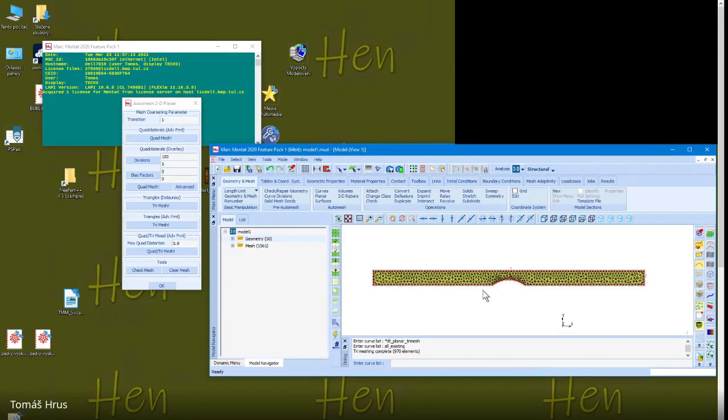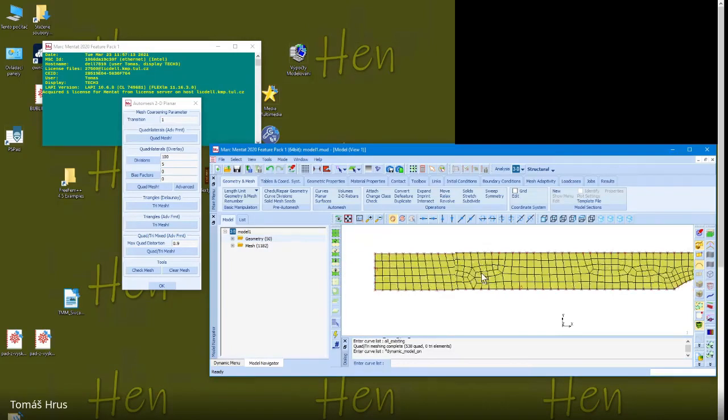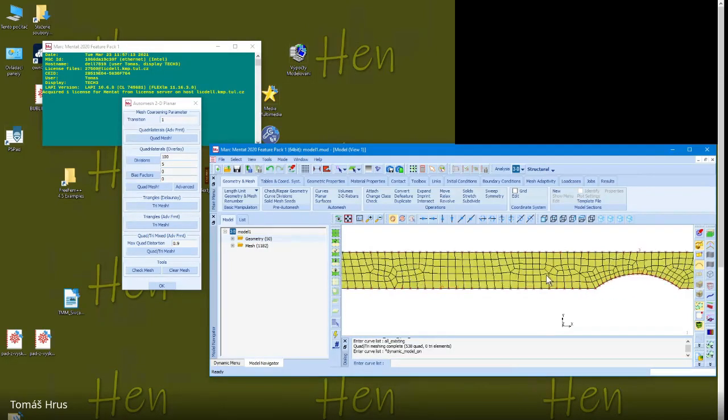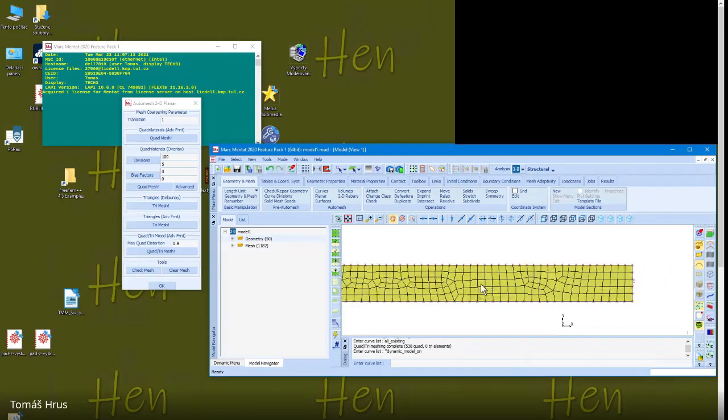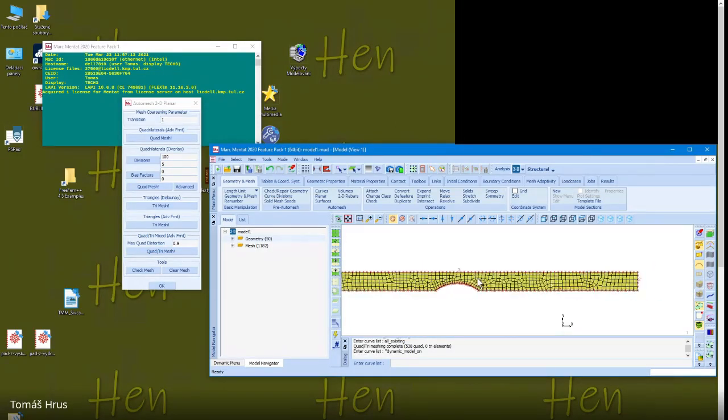So in the planar case, you can use quad mesh or triangular mesh or a mixed mesh. You can see they are mostly quads, and maybe somewhere there is a triangle. In this model there is not, but there can be, because I use this possibility. So it's up to you which type of elements you use and which mesh you will produce.